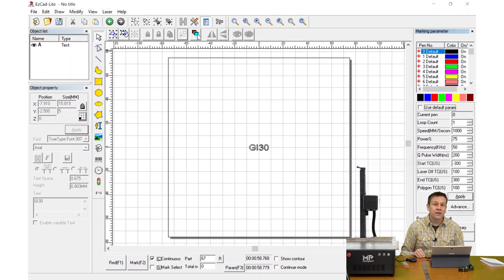There's also going to be a fourth setting that I'm going to be utilizing, and that's because this machine has a MOPA power supply, and that enables a Q pulse width. I recommend, if you're just starting out with a fiber machine, leave this Q pulse the same number and just utilize the frequency, power, and speed. You'll be able to gain a lot of knowledge with that, and once you start becoming comfortable with that, you can start changing the Q pulse width,